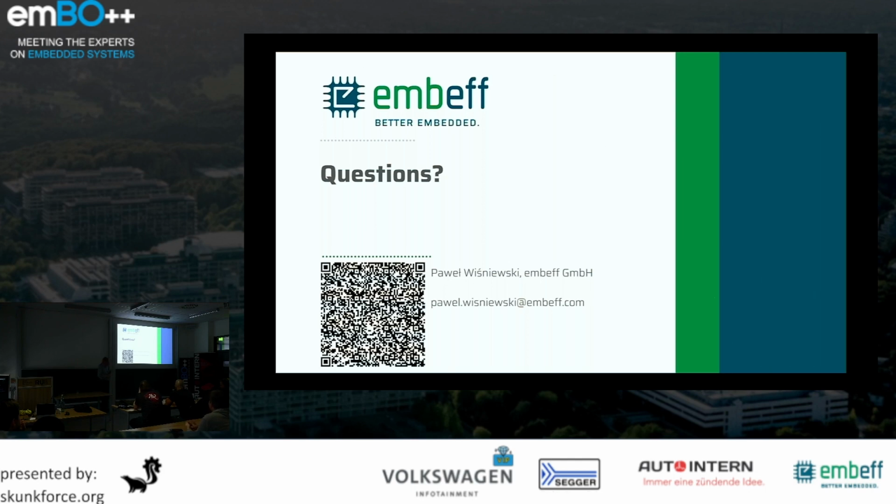But what is also possible, that is part of what Daniel did in his talk, you could test some scenarios, like calculate something in this set new value function that I had. It could, for example, communicate over some bus, for example CAN bus. And then I could produce traffic on the CAN with some error frames and so on, and look at what kind of influence this error handling has on my execution time, depending on this condition. Because for worst case execution, we need this worst case. So we need error handling that usually can take longer, because we try to send this frame a few times and so on. So it would be possible to combine it also with the periphery that is trying to communicate with something on the bus.